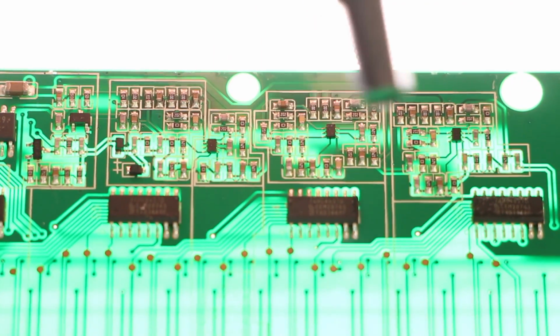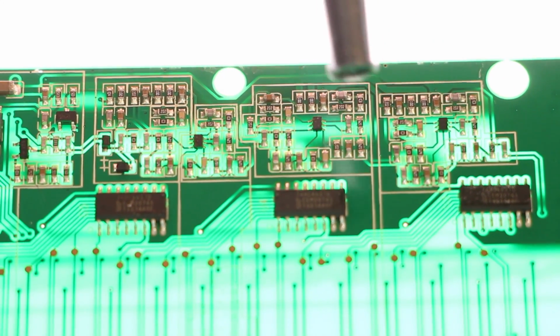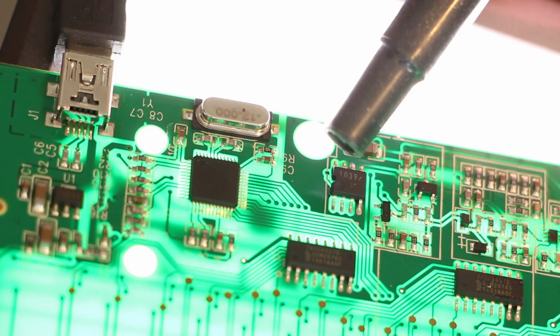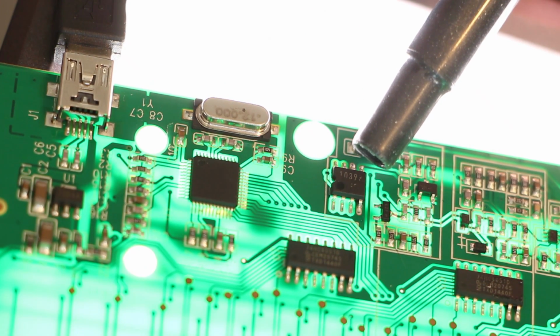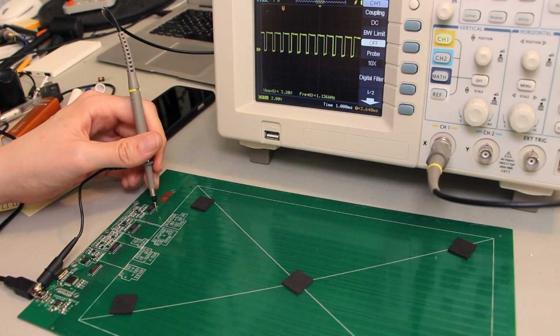The designers have really helpfully added these boxes around each stage of the amplifier design. These first few stages seem to be based on these small 6-pin op-amps. This 8-pin chip that looks like it could be some kind of serial memory is actually the last stage in the analog front end. We can start to get a very rough idea of what the scanning pattern looks like